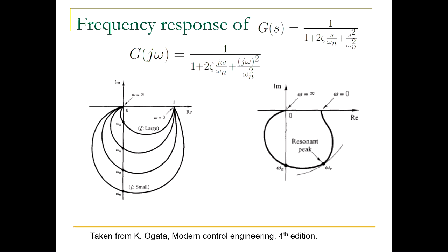In mechanical systems or in electrical systems, there is a thing called resonance. What does that mean? When you hit the system with an input of a certain frequency, the output magnitude is amplified a lot. Well, if you have low damping, we saw that overshoots would go crazy, right? Low damping, you have larger overshoots.